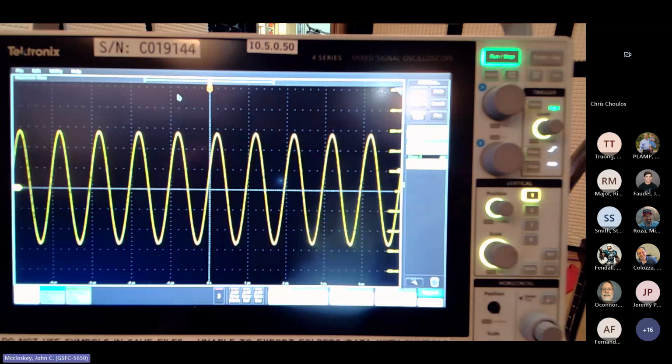Okay. So this is very important. So why am I telling you this? There's always a reason. This is very important for understanding how the CS114 signals make any sense, because most of the time you are not injecting into a 50 ohm load. Even in the calibration fixture, you're injecting into 100 ohms, because you've got a 100 ohm or 50 ohm dummy load on one side and the 50 ohm load of your measurement device on the other, which we'll get to next.